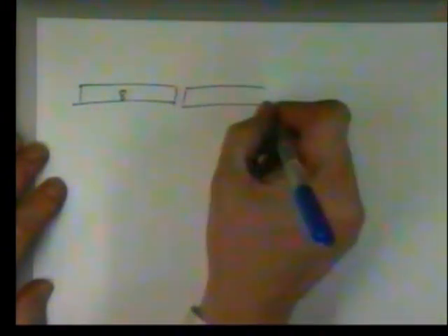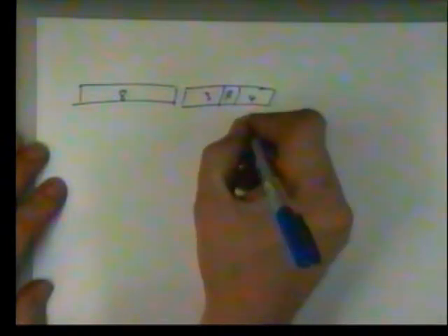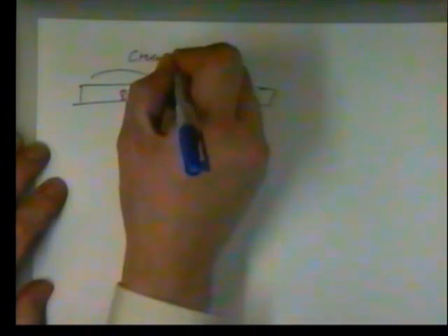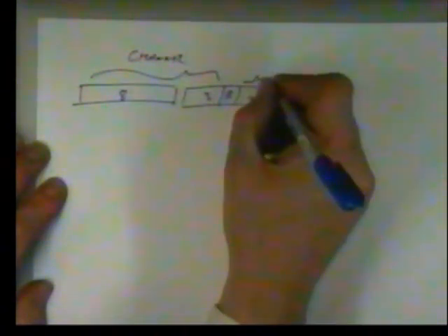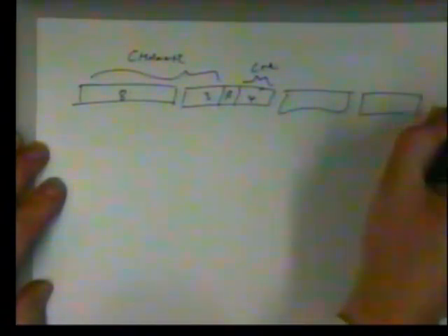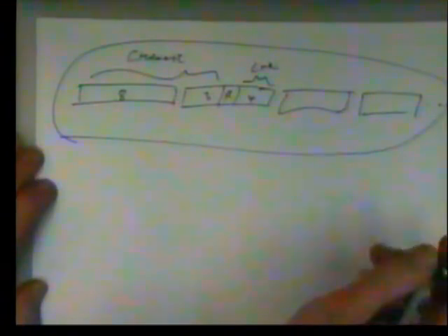So the overall structure is you get 8 bits, 3 bits, the response bit, and then you get 4 bits there. Those first 11 bits are the channel address, and then you get 4 bits, which is the length, and then that number of bytes will follow, up to a maximum of 8. And that is the whole structure of a CAN bus frame. It's extremely simple. And what's nice, because it is so popular, there are a large number of devices available off the shelf that do this for you.